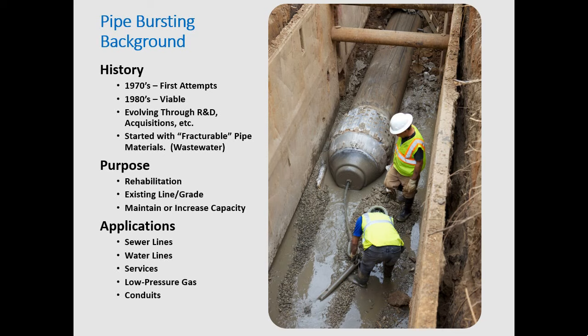So kind of the applications that it's used on, we talked about it being sewer. Water is really gaining popularity, especially in the state of Alaska. It's been used quite a bit there, not as much on the sewer side. They're using it now on services. There's been technology, I'll talk in a bit here about a new manufacturer that's kind of downsized their stuff and able to use it on small sewer services and water services, and they're using pipe splitting. Low pressure gas is using it quite a bit, not as much here in Anchorage, but it is being used, and then conduit. So it's got a lot of different uses depending on what type of utility or pipe you're trying to replace.